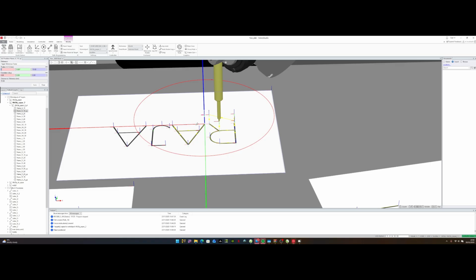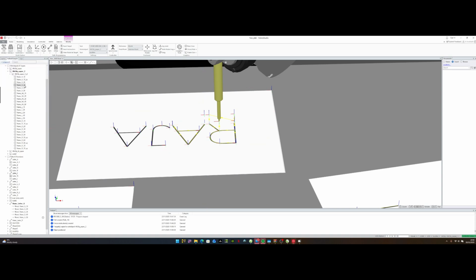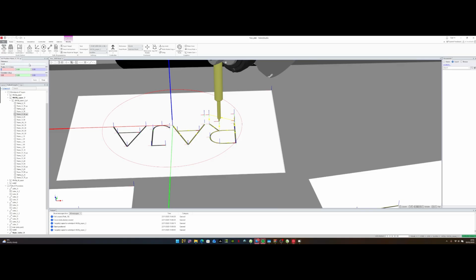Let's do the same for, this is 1, 2, 3. So for 30, we're just going to duplicate this again. Up. Now we're going to right click, modify target, set position, change the reference again to target reference frame, and then position, we can just put 15, apply. Okay.